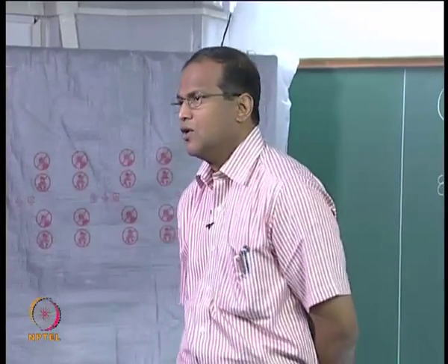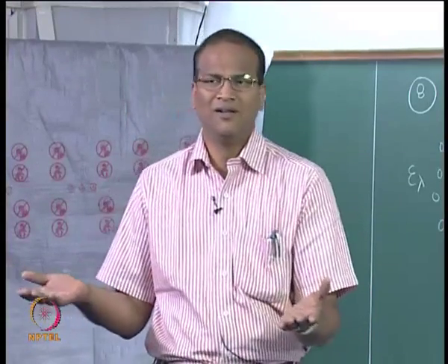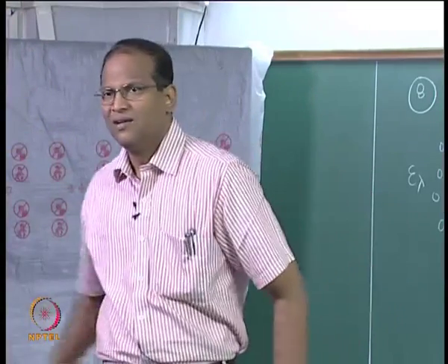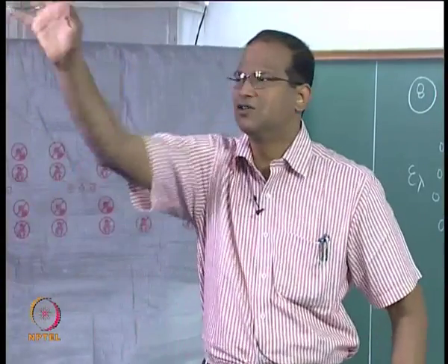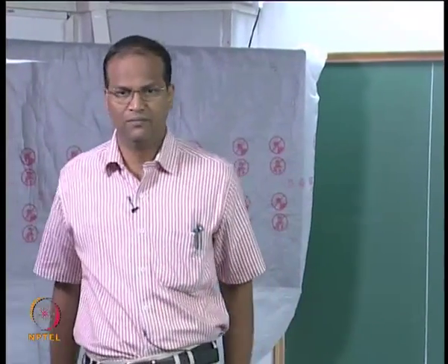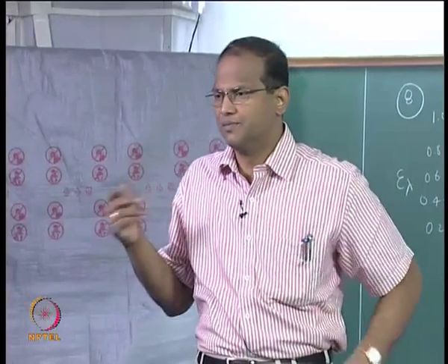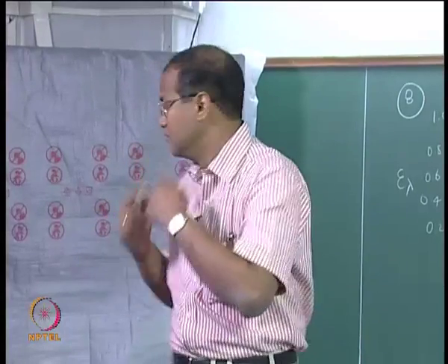Okay, shall we start solving? So the story is from epsilon lambda you have to convert it to epsilon, and then you have to use the Stefan Boltzmann law and then look at the power consumption. Some critical data is not given, the area of the bulb, but needless to say area of tungsten bulb is same as area of a zirconia bulb, all that you can cancel, right? T is also the same, T infinity is the same. So the power consumption will be a direct ratio of the emissivities only. Then part C is you have to look at what is the radiation which is produced in the visible part of the spectrum.